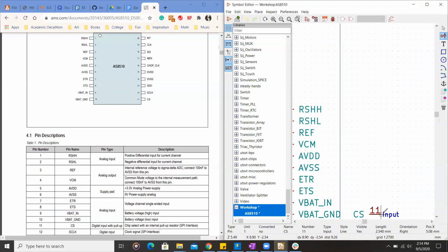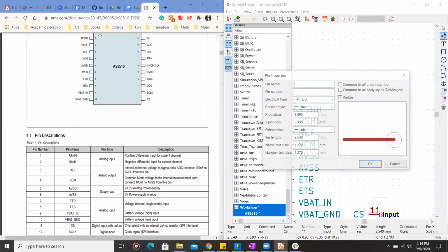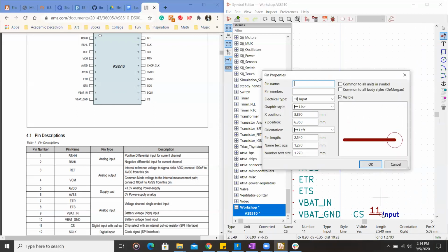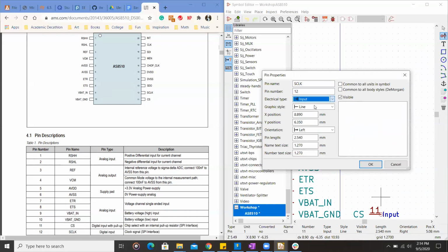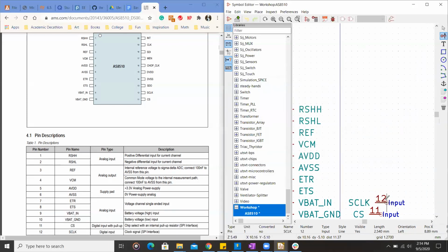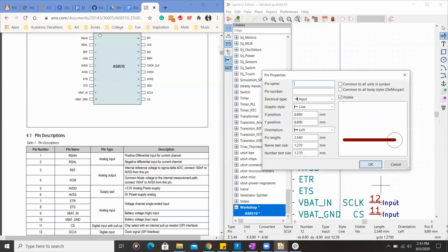So that was just rotating it, because you want the pins, these little circles, to be facing outwards, not inwards. Generally speaking, I don't want to say anything with 100% certainty, because I'm sure there are exceptions to a lot of this. But generally, you want all the pins facing outward because you want to make sure you're connecting to something external to the symbol, not internal to the symbol.